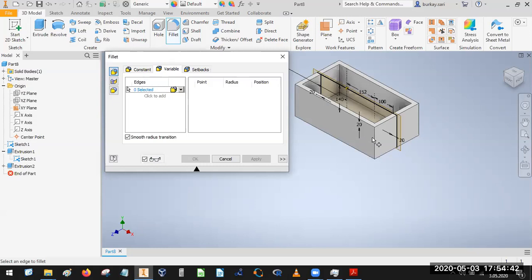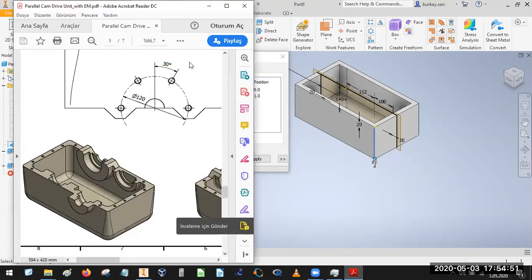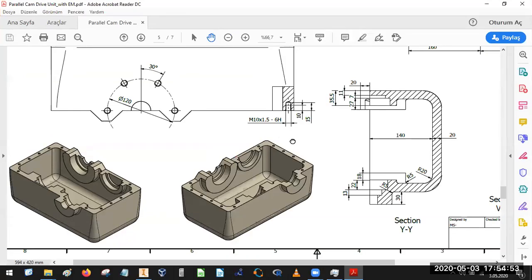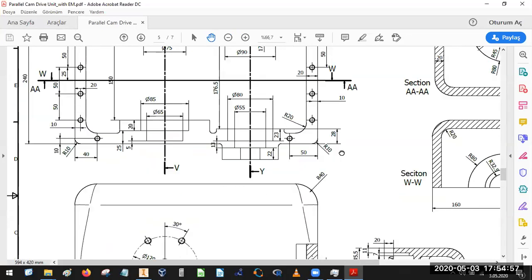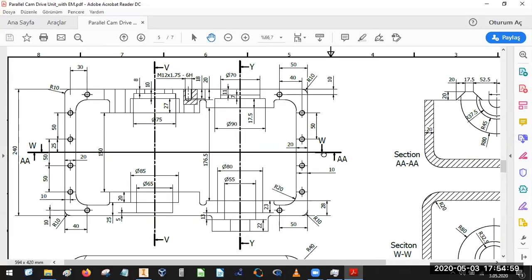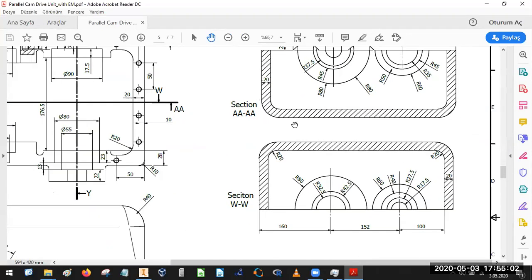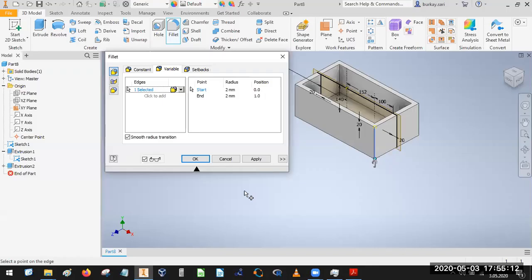I would like to have first this section. The next thing, I will enter the fillets. Here, what I have from the top side, as you see, we have 10 millimeter, and the other one we do not see. Let's say we can just make 30 millimeter, which is the same in size as the wall thickness.